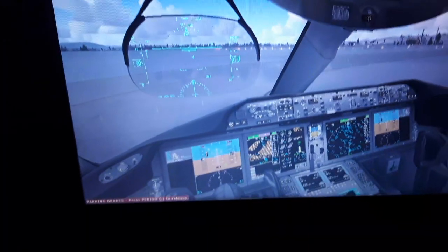We also have the flight plan, which is going to be displayed as I told you using the waypoints. So we have the navigation aids displayed in the navigation display: the VORs, ADFs and DMEs, the VOR stations and the ADFs and DMEs. Also the waypoints, which are horizontal and vertical navigation fixes the aircraft can fly through. We're going to select some waypoints that are going to be displayed in the navigation display. They're also going to be connected from the flight management computer in the flight plan. We will create the flight plan in the flight plan page.